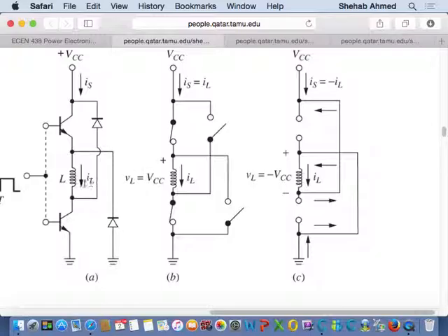So what's going to happen here? Inductor current has to find a place to go, right? So where will it go? I put these diodes around it. So current will flow from the inductor. Current will not change polarity, right? It can go through this diode. It will forward bias this diode because I'm pushing forward current through the diode. So this can turn on.